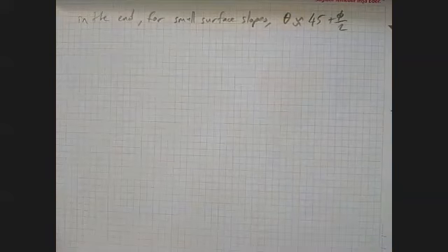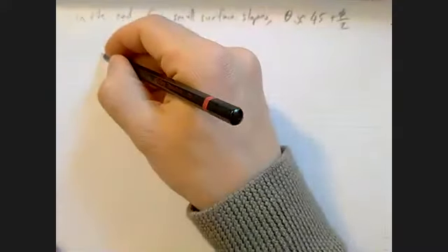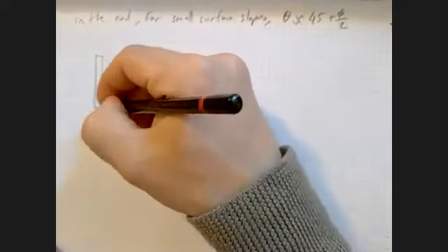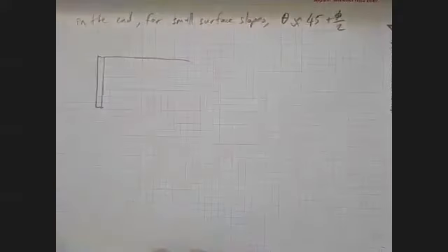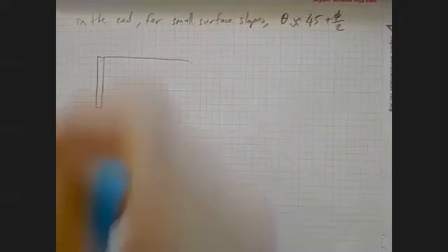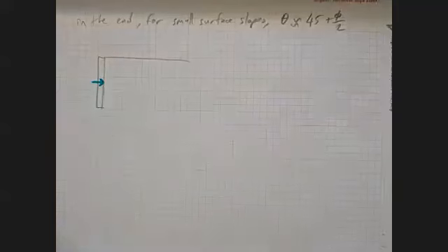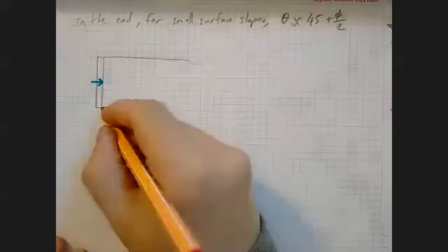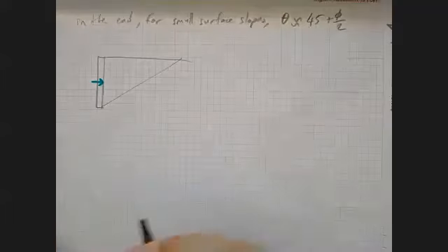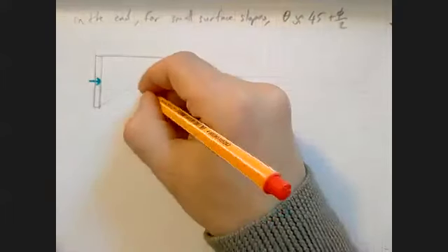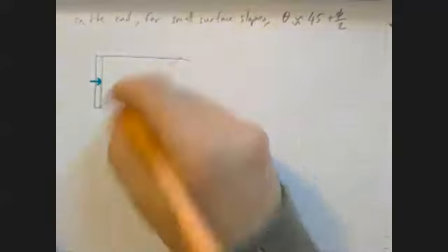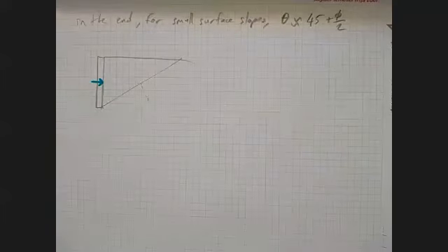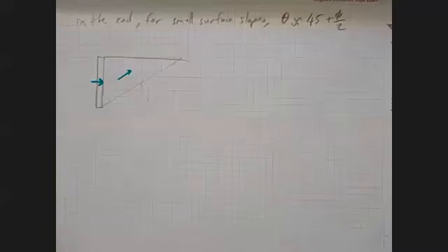Now, you could do the same thing for passive case, because I can go ahead and put my wall, and this time move my wall inwards to the soil. Then what I have is going to be this. And this time the forces, the direction of the forces will be reversed, because this is going up like that.